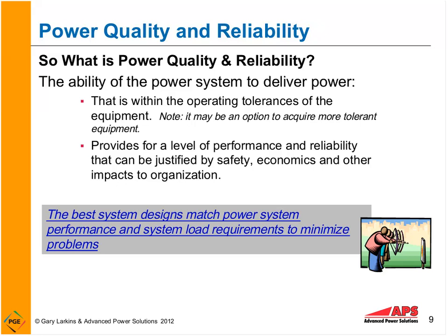In other words, if I buy a drive, is it designed to operate with the level of fluctuation in power that I have on my power system in my facility? That fluctuation may come from variations in the power grid. It may also come from fluctuations that occur, let's say, by startup of a large load within my facility, which may cause what's called a voltage sag.